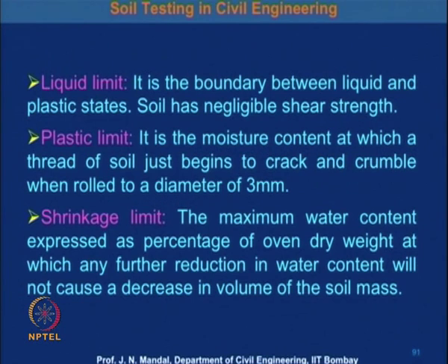Now, what is the liquid limit? It is the boundary between the liquid and the plastic state. So, soil has a negligible shear strength. Now, what is plastic limit? It is the moisture content at which a thread of soil just begins to crack and crumble when rolled to a diameter of about 3 millimeter.